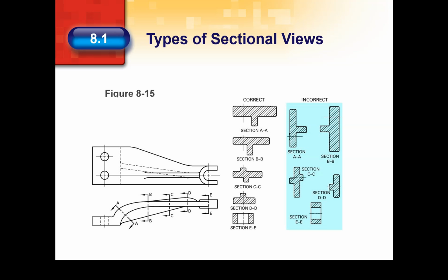Use bold letters to identify the removed section and its corresponding cutting plane on a regular view. A removed section can be a slice section, the same as a revolved section, or it can show additional detail visible beyond the cutting plane. You can draw it at the same scale as a regular view or a larger scale to show greater detail.